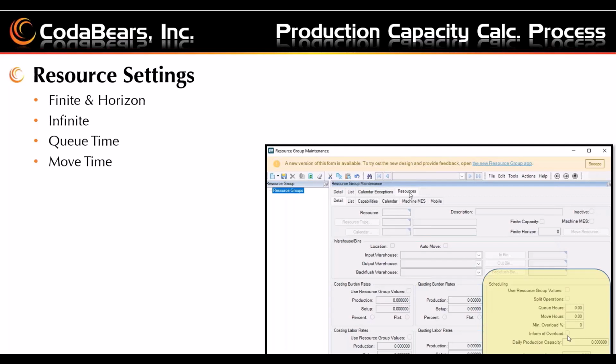I know some of the versions have addressed or tried to fix that. I would almost say right now, double check the setting, run the scheduling engine, change the setting on the resource and run it again to make sure that, yes, your version or patch doesn't have one of these issues with shift problems.